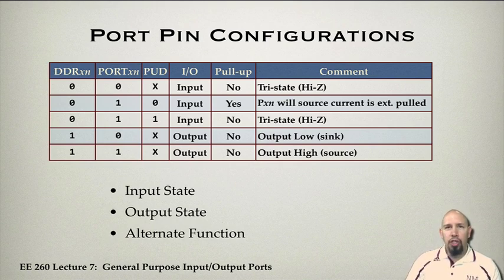That would be similar to the pin mode where you say input pull-up. When you say input pull-up, that's actually setting it into this state. So this is the state we go into when we use pin mode input pull-up. Now you have this other option that can occur, which is a different high impedance state. So this is a possibility, but these are the two that are most commonly used.